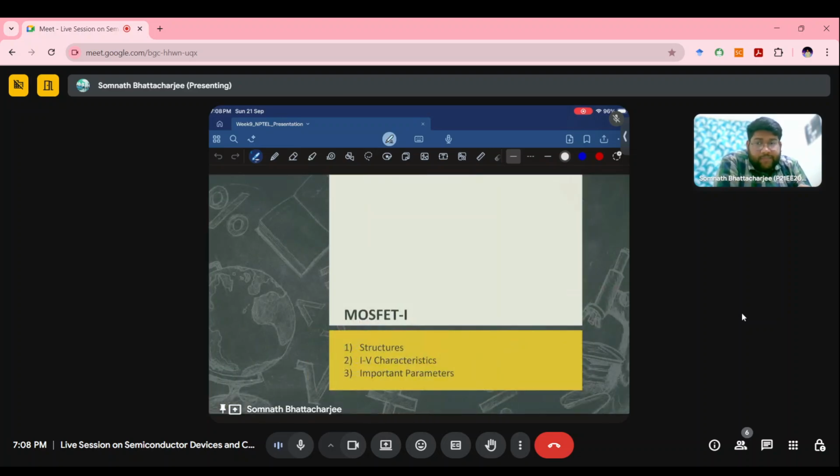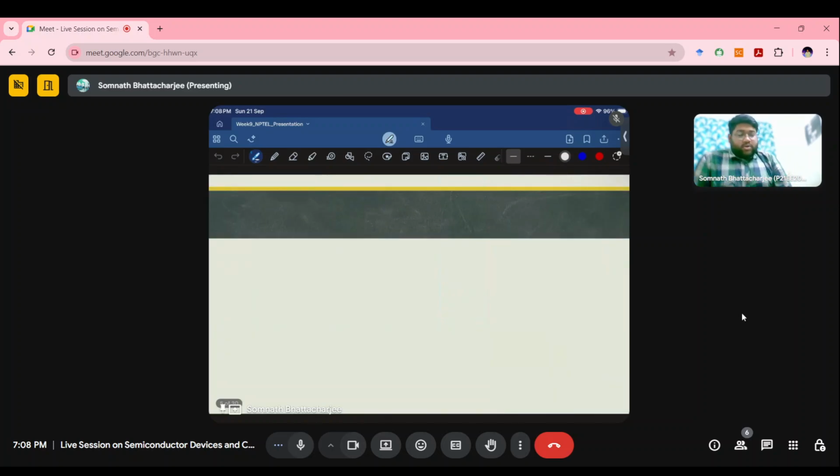So this week, throughout the lectures, what we have learned is the types of MOSFETs, which kind of MOSFET has a different structure, and the IV characteristic of this MOSFET. There were several derivations of the equations, and key parameters like the mobility, VTH, the channel mobility, the channel thickness, and depending on the channel sizes, that is the width and the length, and there were the subthreshold slope, subthreshold swing, and this kind of parameters. So let's move on to the basic recap of the course.